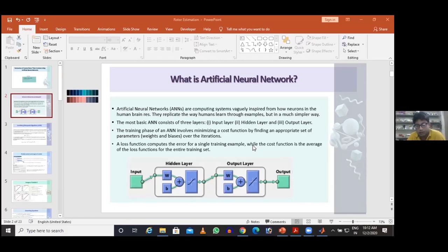which will control the flux, the field, and the armature current in an isolated manner, and you can achieve the decoupled control of torque and RPM. But there is some disadvantage in the DC machines because it needs brush. So in high power machine, it can create some flash or spark, because it's a mechanical sliding contact. So it cannot operate in hazardous areas like refinery, nuclear plant, all those chemical industries. There we cannot use it.